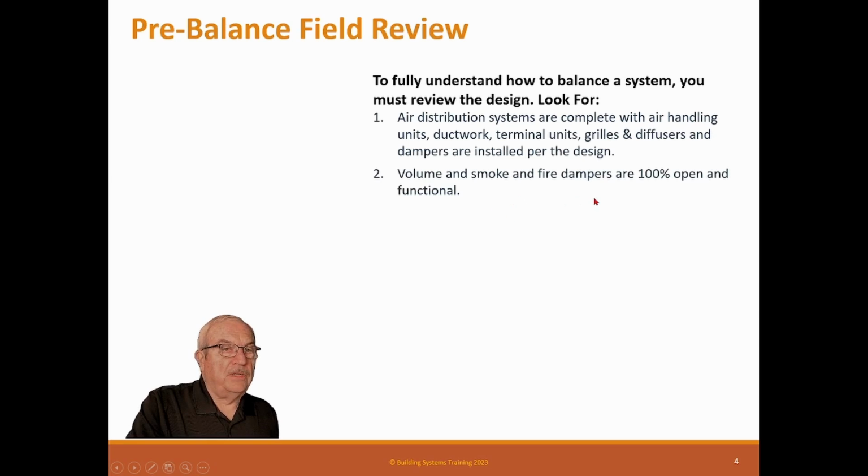Volume and smoke and fire dampers are 100% open. Now you're going to get tired of hearing that. I know you're going to get tired of hearing that because we talk about it on every single system, but it is the number one thing you have to do to actually balance the system correctly. Clean filters is another thing you get tired of hearing about.